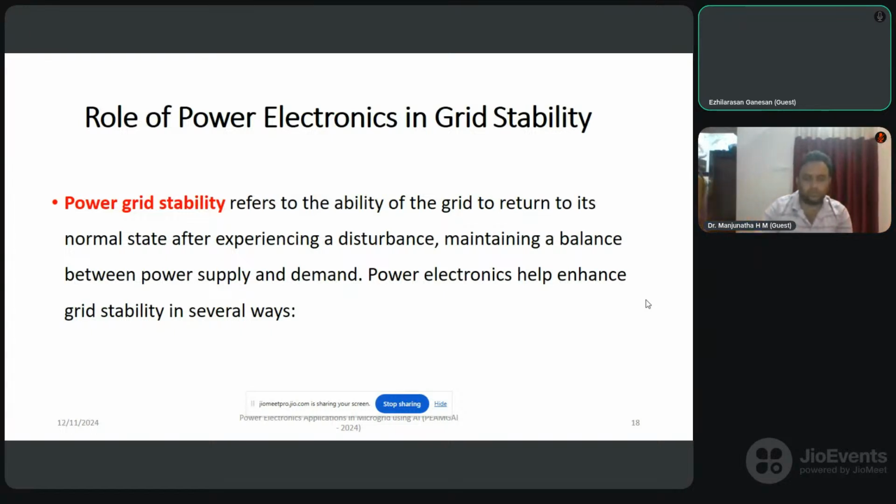If the frequency drops, one of the machines will pull out. Let us say the thing is happening in AP, but the Mettur power station in Salem may pull out of synchronism. When that machine pulls out of synchronism, that machine will be lost. Already the load is heavy, so when one machine is lost, the load is transferred to the other machines. The next machine in the network will similarly go, very quickly. It is a cascading effect. Very quickly, the machine in Kerala may go off, next the machine in Krishnarajasagar power generation plant may go off. So this cascading effect will pull down the entire grid.